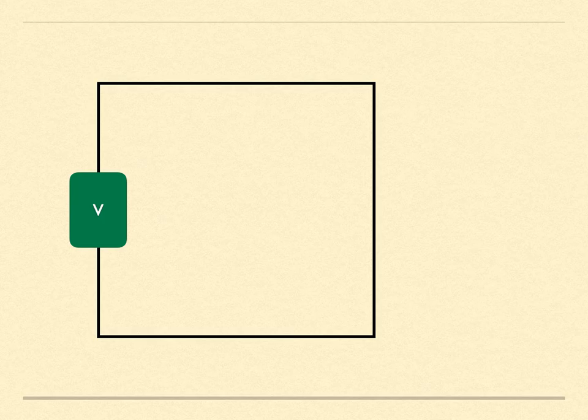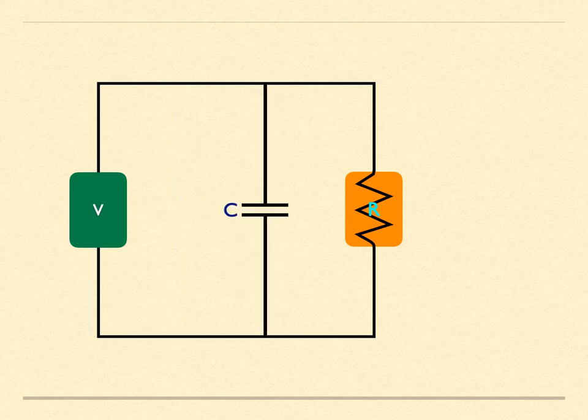The basic parts of an electric circuit include a closed path for the electric charge carriers to move around, a device of some design that creates a potential difference that drives the charge carriers in their motion around the circuit, some kind of resistance to the flow of charge, some kind of capacitance that can store electric charge and electric energy, and some kind of inductance that opposes changes in the flow of charge and stores magnetic energy. Every electrical circuit possesses these properties. Sometimes it's by design, in the explicit inclusion of discrete components, but if not included explicitly, there is always unavoidably these properties present to a greater or lesser degree.